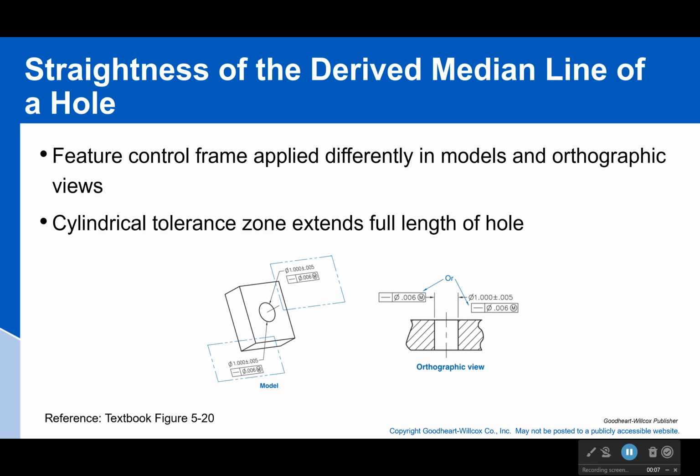We did a cylinder last time, let's talk about a hole. So we want to control that derived median line, and yes, holes have one too. It's just the center of the hole at all points.